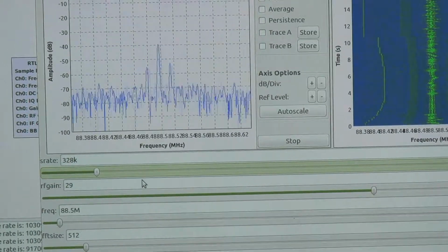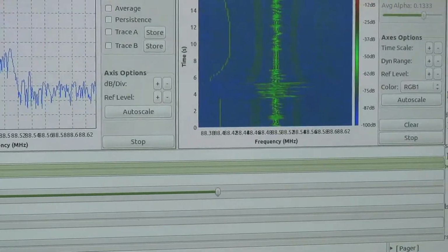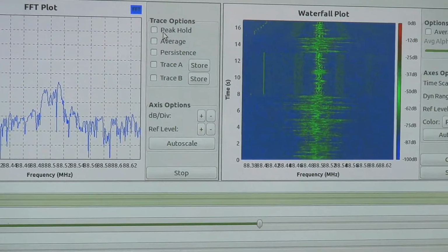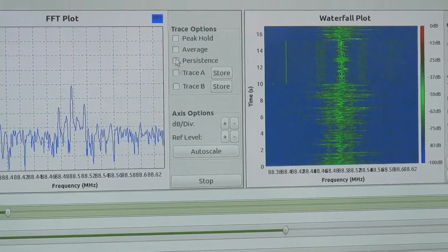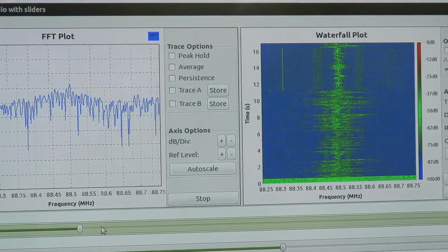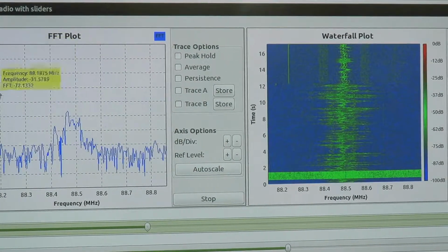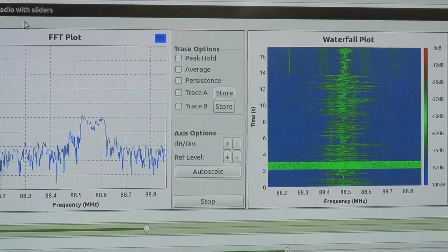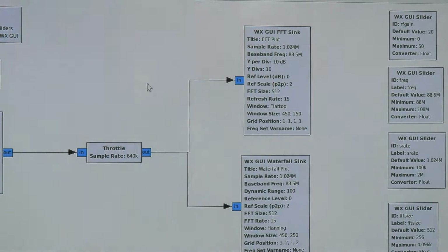John, with your peak hold, you could tell if they're over-deviating. Yes, I could. So, well, the peak hold. Tune into the Stanford. That's right. So there you are, and it's actually not a bad spectrum analyzer, and I've checked it for linearity. The amplitude scale here is actually quite accurate, and I've got that one set up for sort of narrow band.